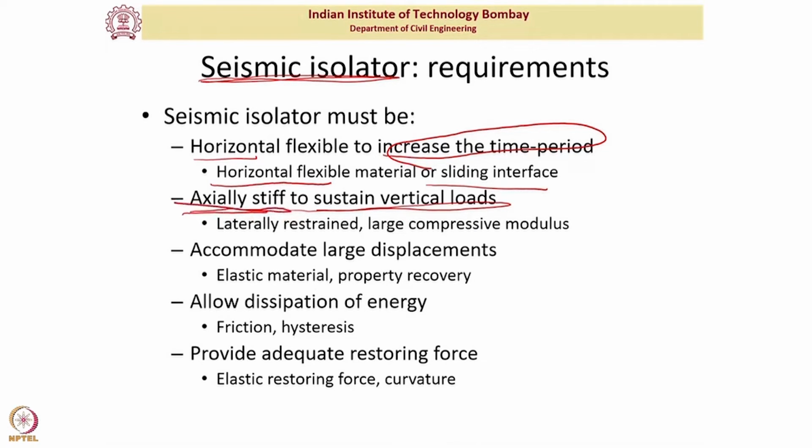Now how do we increase the axial stiffness? We will look at that later, but basically, if you have a simple column with axial load, I know that a shorter column would have higher buckling capacity, or if I provide lateral restraint, it would have higher capacity.